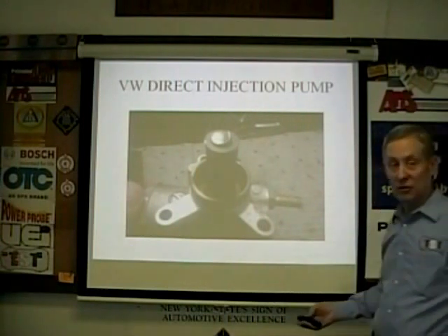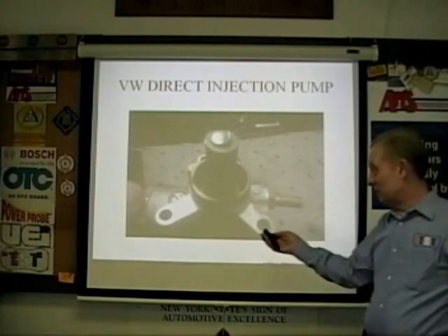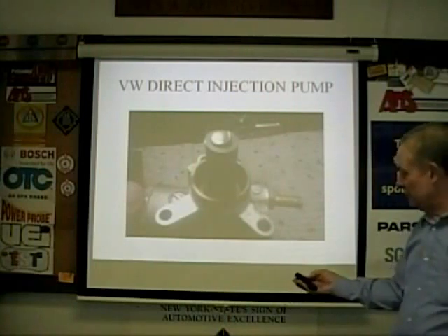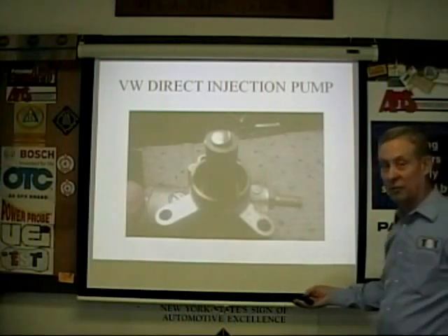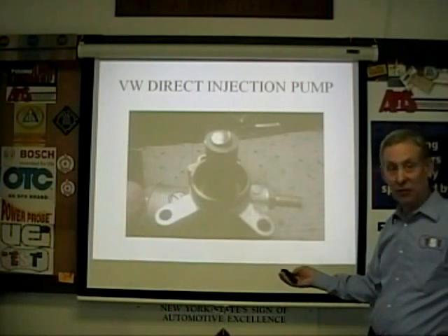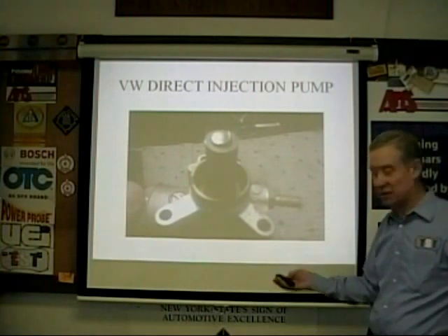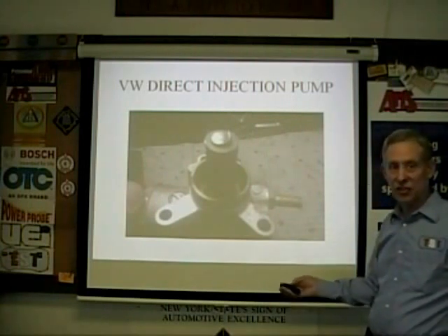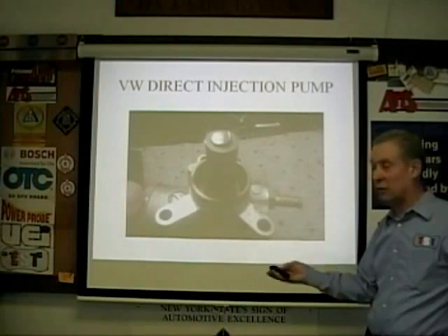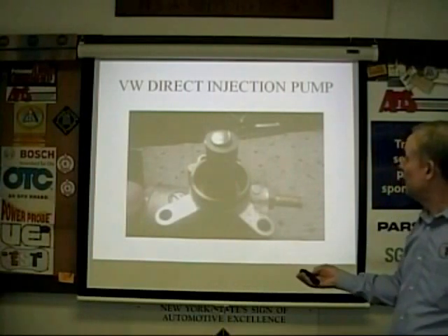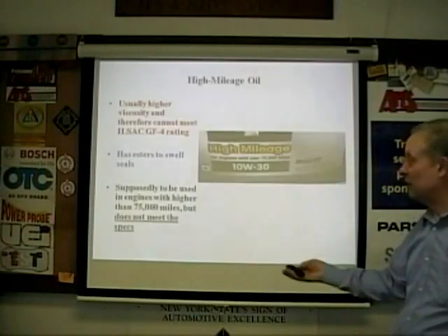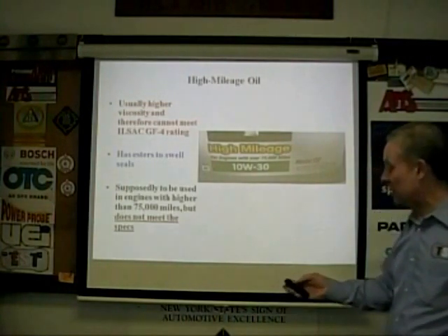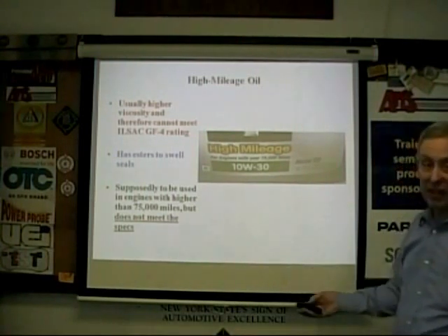So when some of our customers go to these quick places, that's where this damage actually happened. Yes, 1995 cheapy oil changes? Bad news. If it was a quick place that used the right oil and the right filter, nothing wrong with that. But if they use the wrong oil and the wrong filter, you're taking your chances with it. So you must educate your customers on that. The customer must be educated. They can't just trust. This case here was a quick oil change place that did this, and in fact, there's a lawsuit on it right now. They're going to end up buying the motor, because there was so much metal in this motor, it was everywhere. There was a lot of damage in this motor. It wasn't just the cam that got done.